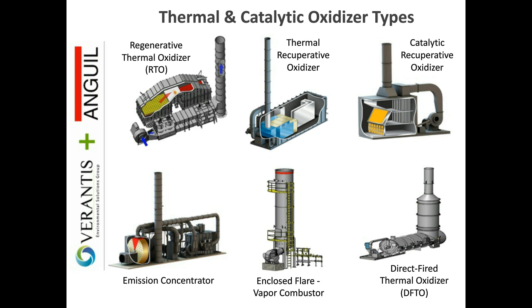So what we're trying to do is achieve very high thermal efficiency, again, to reduce operating costs. The DFTO, or the enclosed flare, have no internal heat recovery. So they tend to be used on very low air volume and very rich hydrocarbon or solvent streams.